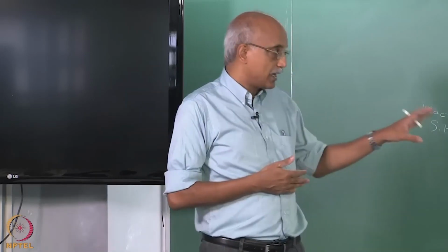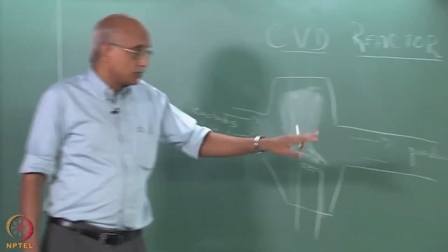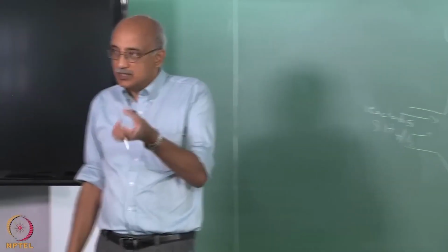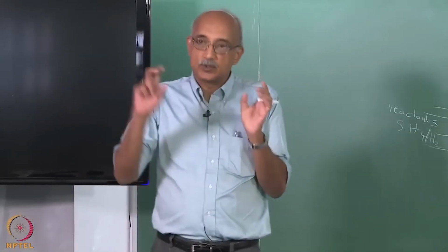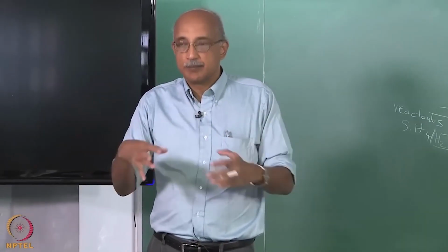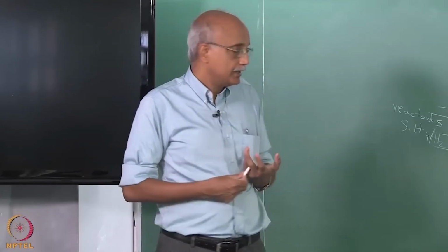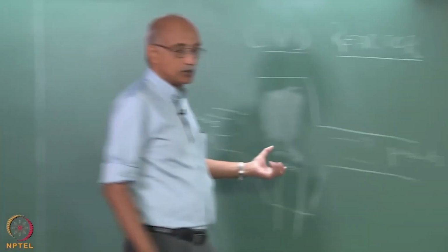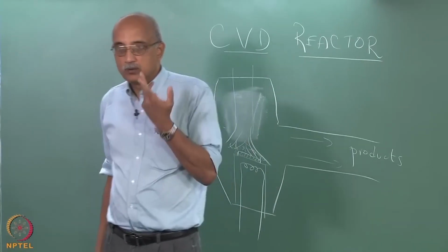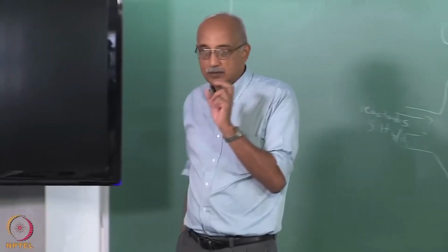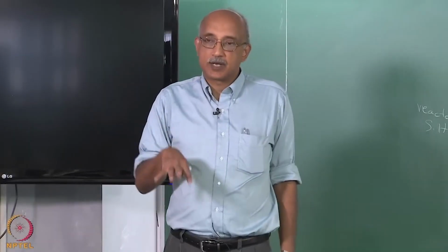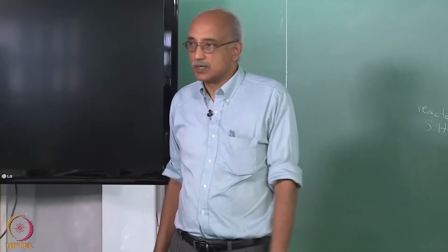And so, it is important to have this in situ inspection system, but if you have that, obviously that needs to be coupled to the control system, because as you see things in the film that you do not like, you have to tweak the control parameters so that you bring the properties of the CVD film back to where they should be. So, ideally you want to provide almost an endpoint control. As you make a film, you inspect it, if it looks okay, go. If something looks like it is not where it should be, then you immediately provide feedback to the system so that the appropriate parameters get adjusted and you bring the process back into line.